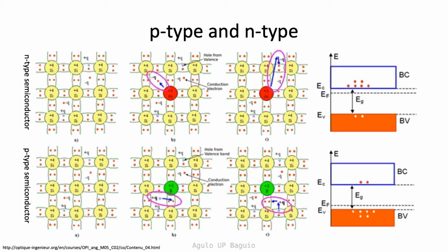The energy of these holes is slightly larger than the valence band. Therefore, the new states created by the hole is the Fermi level and is represented by the dashed line near the valence band. Electric conduction occurs in a p-type semiconductor when an electron from another adjacent silicon occupies the hole. The electron that has now moved has left a positively charged hole. It will then be occupied by another electron from another adjacent atom, and it leaves behind another hole. Thus, it would actually seem that the hole is moving and behaving just like how electrons move around.